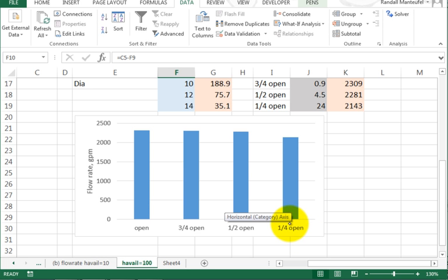We're going to get to that concept. It's really not covered in this book very well, or if at all. That valve doesn't have much authority over the system, but it's not supposed to. It's a gate valve. It's not a control valve. But we'll look, if I have time, at the valve authority. When you buy valves to put in, if they're supposed to control, they need to have authority. Meaning, even when fully open, they're going to have a significant pressure loss across them, because when they start to close, they need to really come on strong.